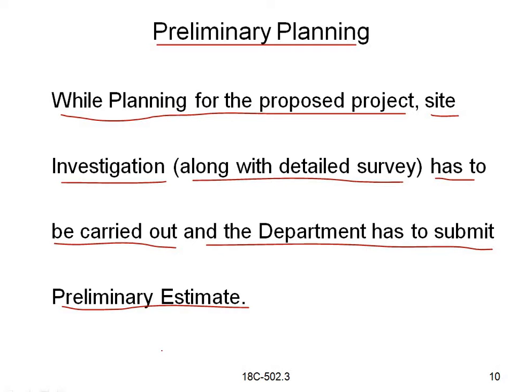Whatever we have discussed in the previous videos, site investigation. So what will we do in the site investigation? Soil testing, availability of materials, availability of manpower and availability of power generation. And moreover the water facility, so everything should be available near the site.